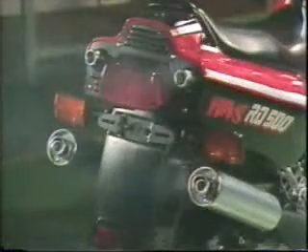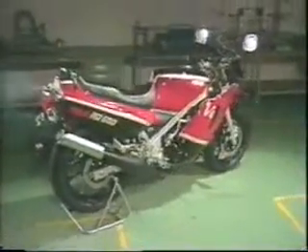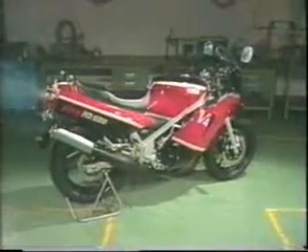Problems at the idle speed range may take a number of forms. For example, the engine may not start smoothly, or the engine may not idle smoothly. These problems can be caused by parts in the fuel system, YPVS, or the oil pump. First of all, you must check if the machine is in normal running condition.